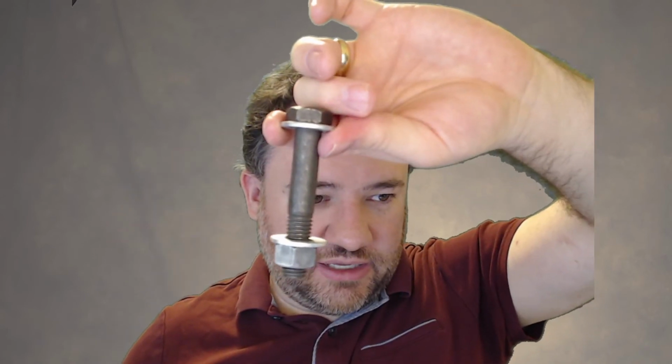Now in steel connections, you'll recall that if the thread is intercepted by the shear plane, we apply a reduction factor. There's no explicit reduction factor like that for bolted connections in wood. And the reason is because we don't typically actually shear the bolts in wood connections, because the wood is not strong enough basically to shear the steel. So mostly what we have is bolt bending, and then the area of the thread will be less critical. So that's what the bolt looks like.